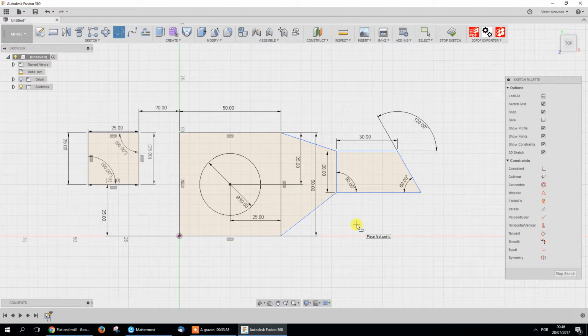Why do I know it closed the shape? Anyone? Because it changed the color. Now it's blue here. If it's opened, it doesn't have any color. So you can, let's say, debug your design from looking at the colors it creates. Sometimes you import files from other programs and you see white areas and yellow areas, and you actually know the problem is somewhere in that area.